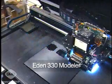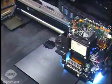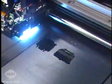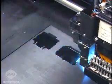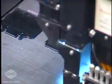The Eden 330 modeling system features 8 heads that contain a total of 1,536 nozzles. Half of these nozzles jet fine droplets of a proprietary photopolymer model material, and the other half droplets of a proprietary photopolymer support material. This system produces extremely thin layers of 6/10,000ths of an inch. Producing such thin layers increases detail, accuracy, and finish smoothness of the models.